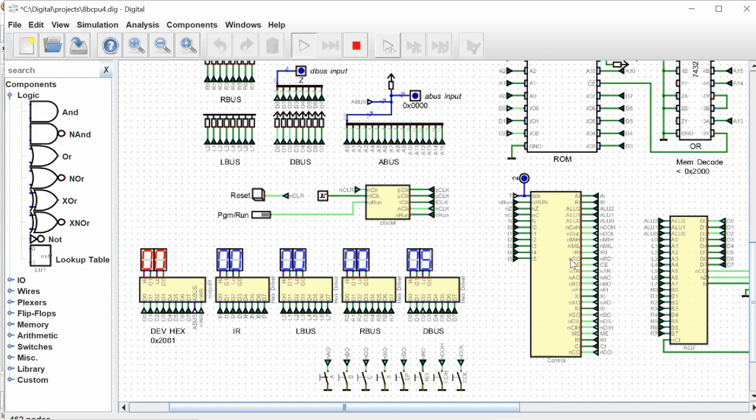We can see our RAM out signal is raised, and our instruction register in signal is raised, and we're going to execute that. The RAM out has 5, which is the load A immediate opcode. Okay, so we'll clock this again.